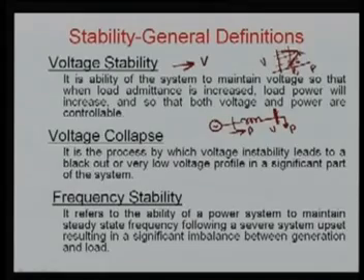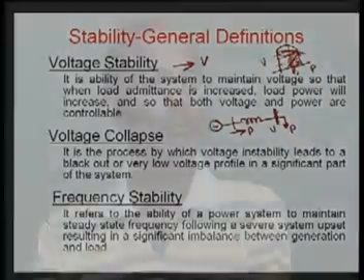And here what is happening, your admittance is increased when your load power is increased. So, this lower section is called unstable, and you can say it is voltage instability in this zone. Only operating voltage should be in the upper zone. So, this is related with voltage. When the quantity we monitor, the quantity of concern, is voltage more than your delta and frequency, then it is called voltage stability.